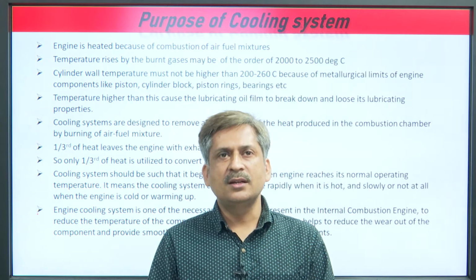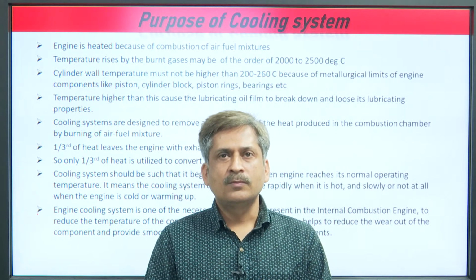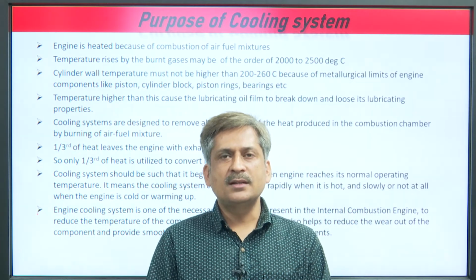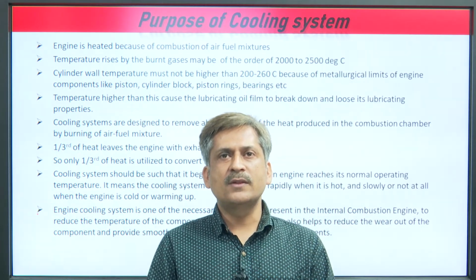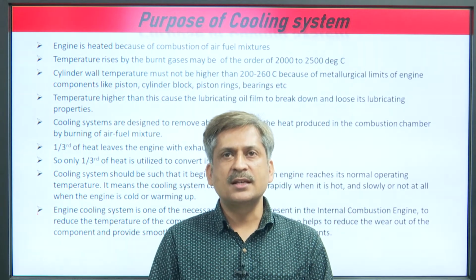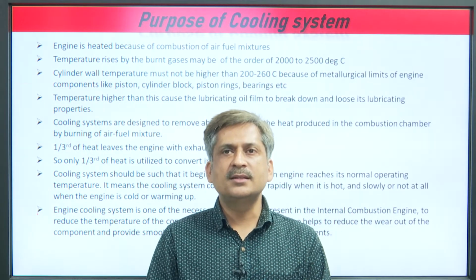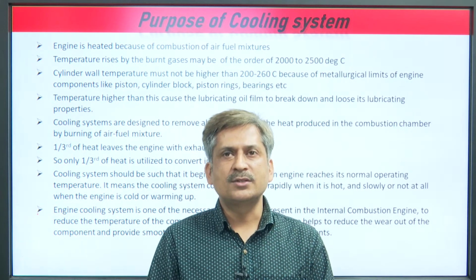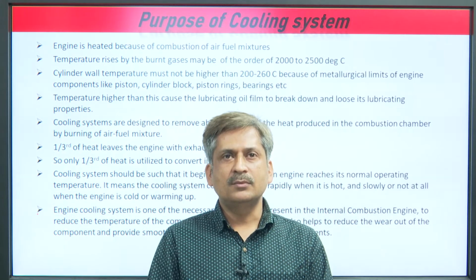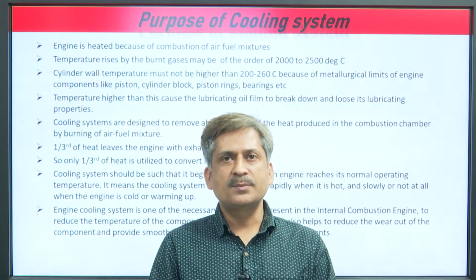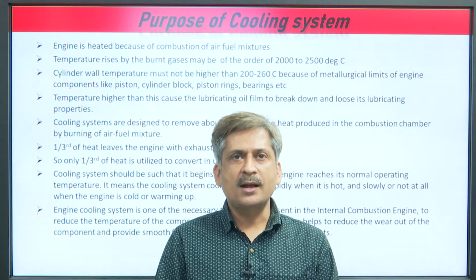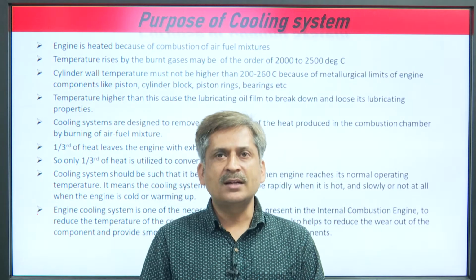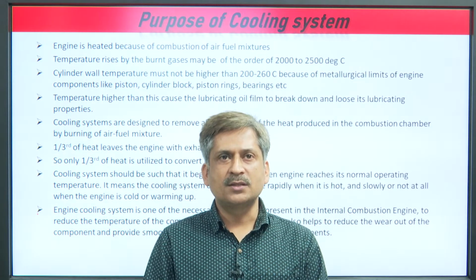The cylinder wall temperature is assumed by the designer to be not more than 200 to 260 degrees Celsius, because of the metallurgical limits of the different components of the engine, like piston, cylinder block, piston rings, bearings, etc. A temperature higher than this causes the lubricating oil film to break down and lose its lubricating properties.